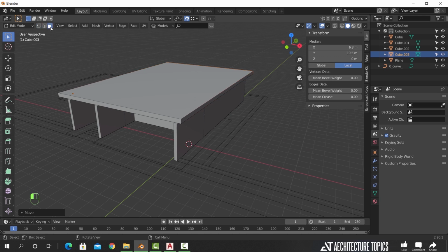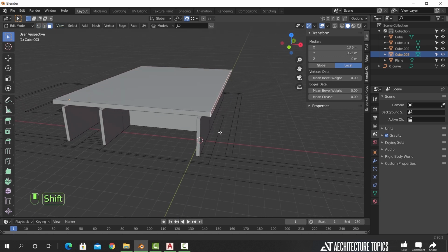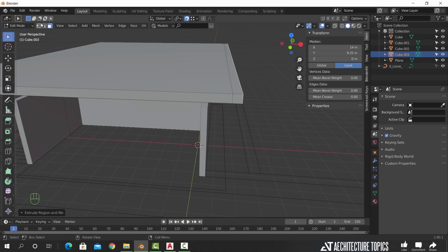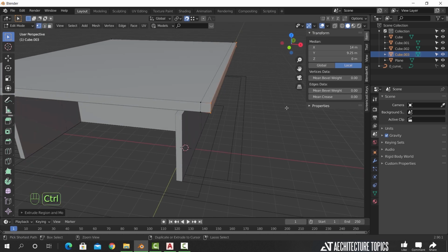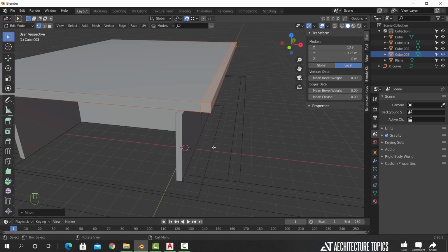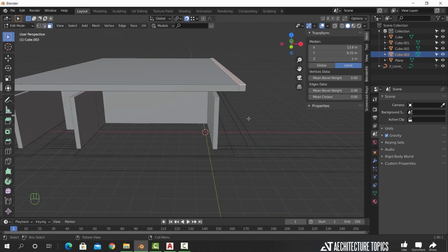Here in this side, we need to extrude this face by the same amount to make a new part that can be extended up. I did here switch back to Vertices selection and pressed Ctrl+ to grow selection, then I moved those vertices back by 0.4. After that, select this top face to extrude it.